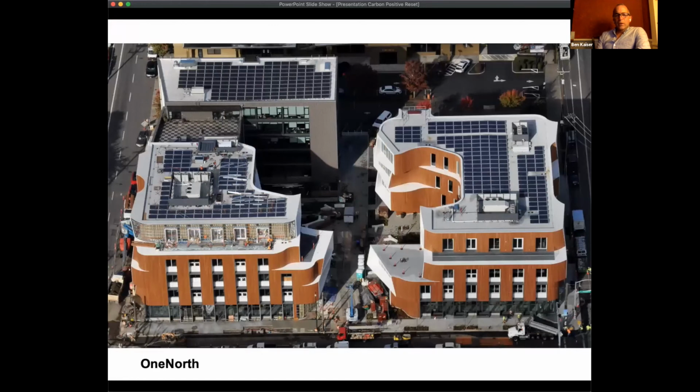This is part of a 3-building complex, all mass timber. One is all mass timber in the upper left. The 2 other lower ones have a combination of mass timber together with shear walls of steel. The upper left has shear walls of plywood. But again, no CLT in these buildings. And then the next one, please.